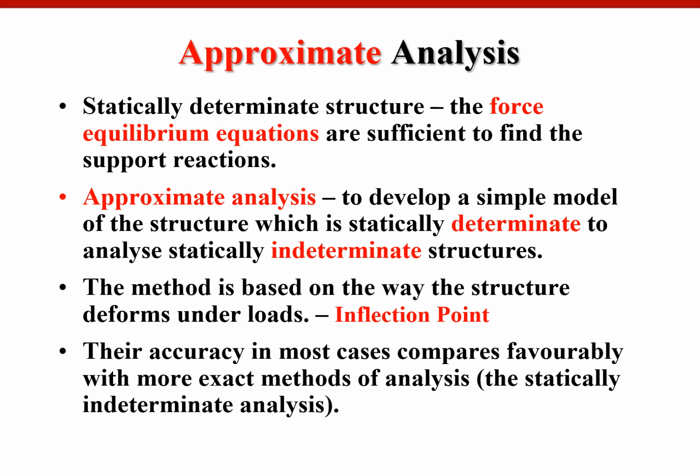So from experience, engineers have found that the inflection point behaves very similar to a real hinge, and we can find out where the inflection points are from our experience. So utilizing that approximate location of inflection point in your structures, in common structures, the analysis result was very exact, practically acceptable range.